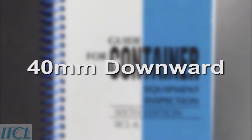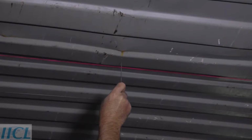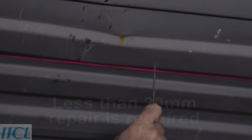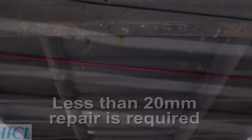As the IICL damage limit is 40 mm downward from the top surfaces of the top side rails, any part of the roof that is less than 20 mm from the string line has exceeded the damage criterion. The inspector measures from the string line to the lowest point of the roof damage. If this dimension is less than 20 mm, repair is required.